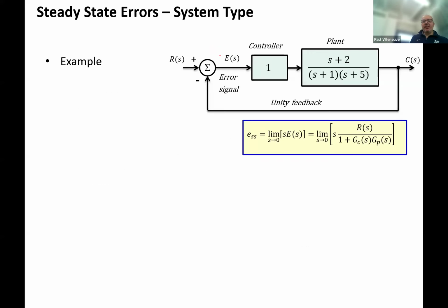All right, one last thing before we start looking at examples. Why do we keep saying this is unity feedback? It doesn't need to be. We can certainly put an H down here, right? There's one reason. It's kind of silly, but it is a reason. If you want to compare your input to your output, don't they basically have to be the same type of signal? If I want this to be RPM, this input had also better be RPM, right? Because you can't get an error between the two.